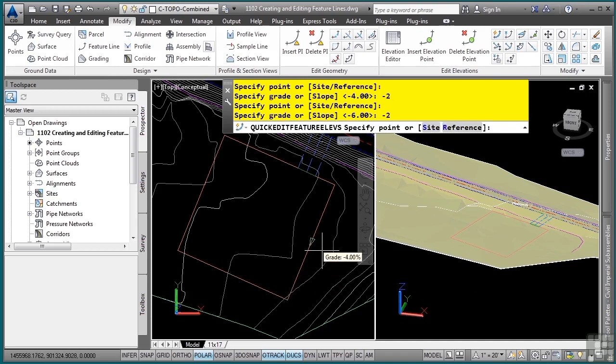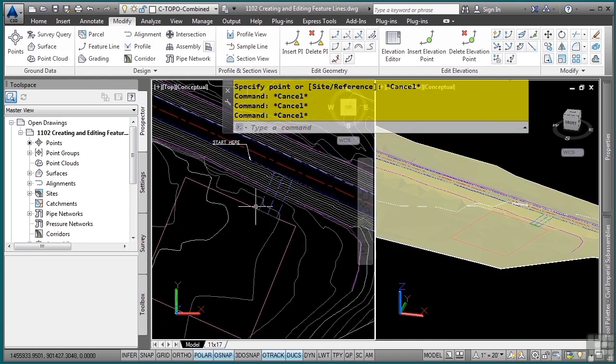I'll even hover over this one, click on that, and say -2 as well. Very simple, really cool tools. Depending on where you select, you can actually even change the elevation from this tool as well. Now that I've graded that, I need to actually join these all together.